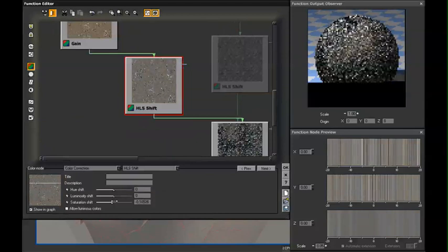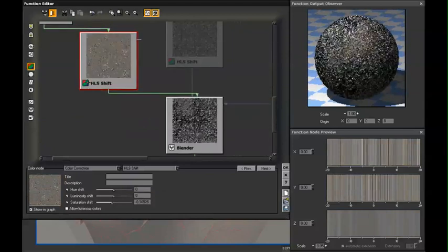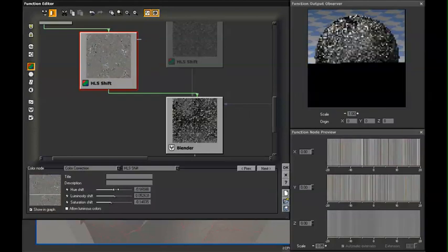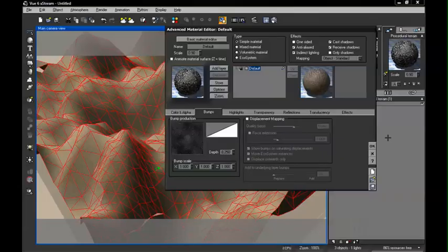That really looks like it's the one that's causing the majority of our problems. Since we're going to be reducing the saturation, I also want to increase the luma value just to bring out some of the contrast. Then we can change our hue if you wanted it to be a different color. I'm going to set that back to 0. Click OK.